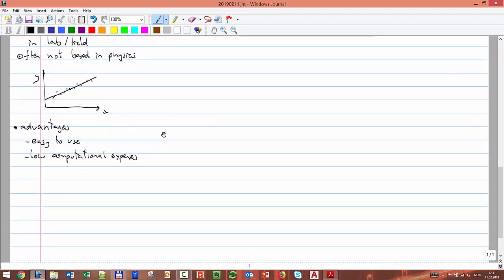However, the disadvantage is that they are limited in applicability. Let's say they did measurements for pressures between 10 bar and 50 bar, and temperatures between 10 degrees Celsius and 90 degrees Celsius. If you want to test something at 100 bar, or at 120 bar, you cannot guarantee that it will give you a good solution, because this expression was calculated for a given range.